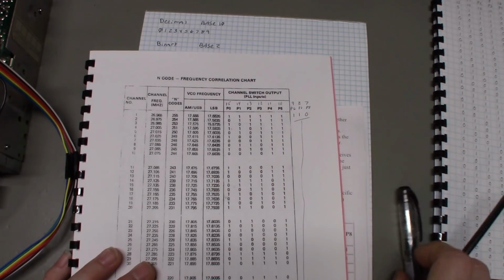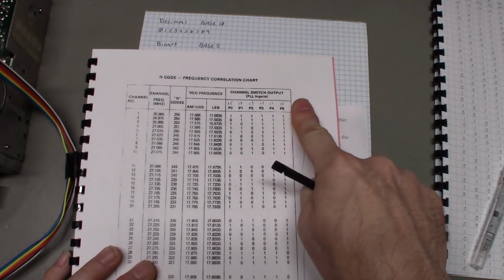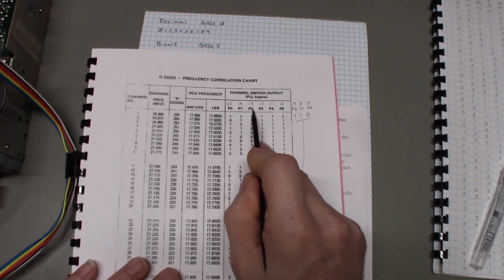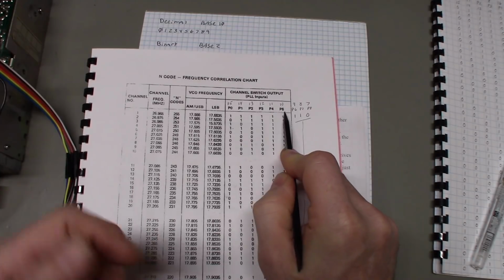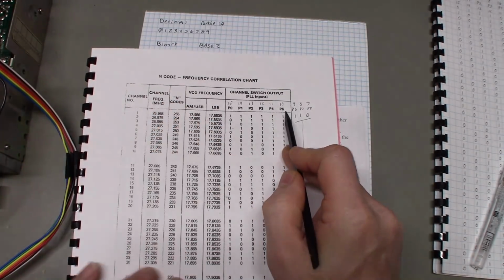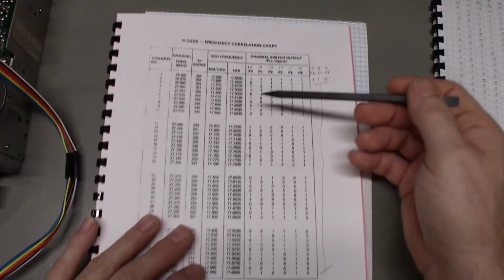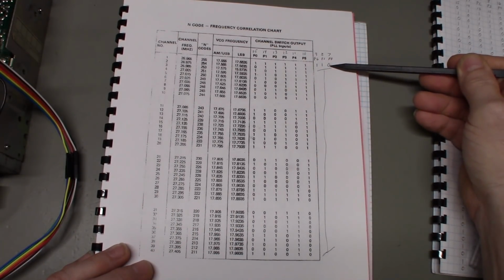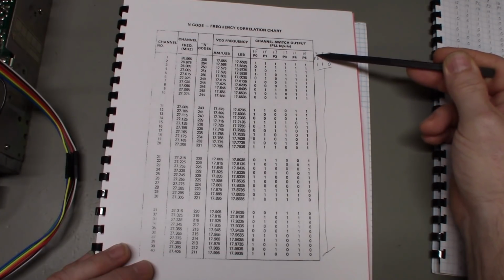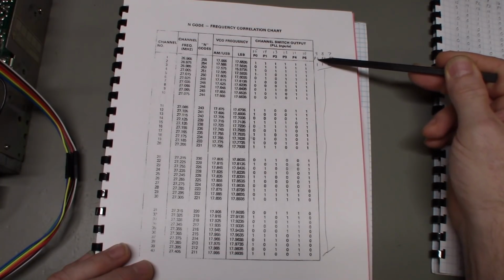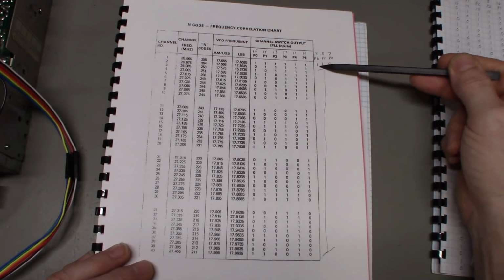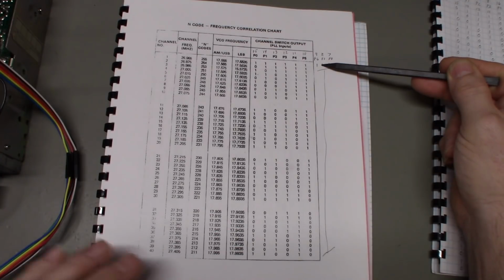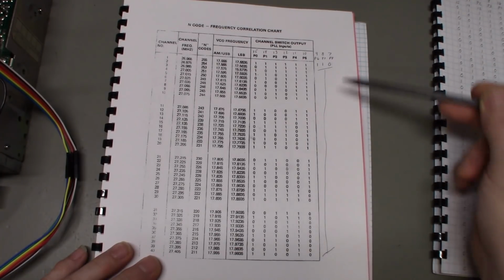Now, another thing you'll notice in this service manual, there's actually 3 columns missing. The reason they didn't write them, because you can see we have P0, 1, 2, 3, 4, 5. But remember, there's a P6, 7, and 8. Well, why aren't they here? That's because in this radio, for the 40 CB channels, those pins never change state. Physically, pin 9 and pin 8, which are programmable pins P6 and P7, are always a 1. They always have voltage there. They're the same for all 40 channels.